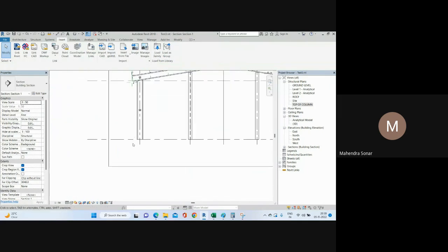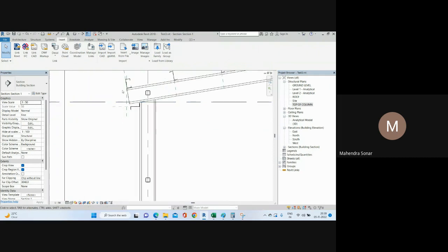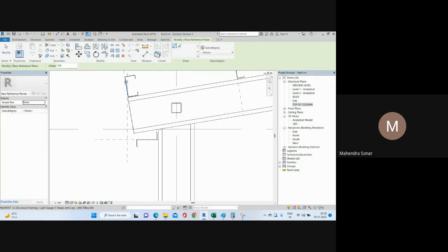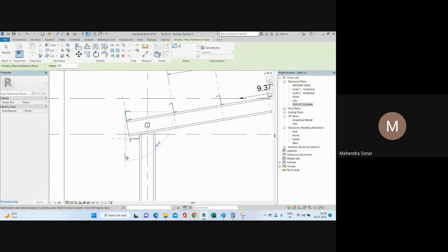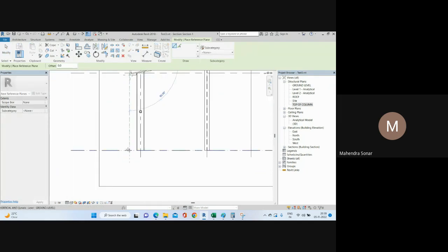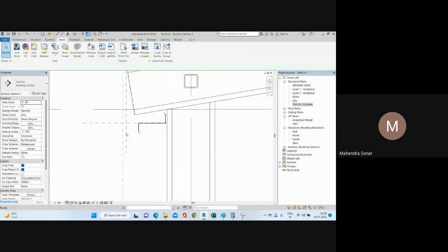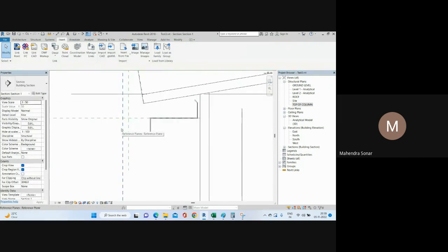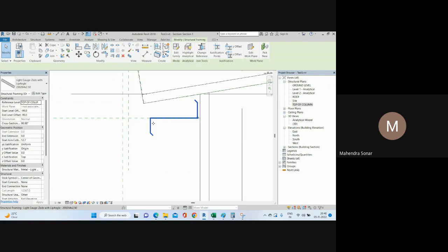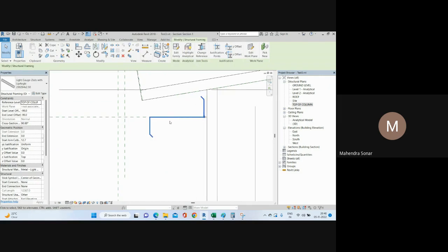Okay, then if you go down, your sheet comes up to here, from this point to this point, right? So if I add the reference line and cover this building, my sheet comes up to here, this part. So suppose my sheet size is 25 mm, so up to here is 25 mm thick. Okay, so you need to increase your side girt size, this Z purlin, or you can move it here and then extend your plate size.